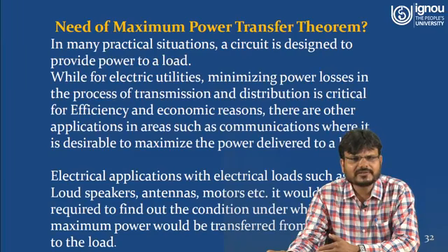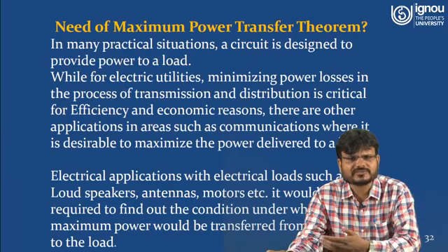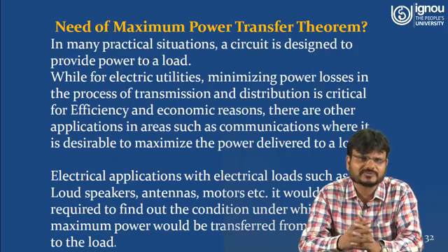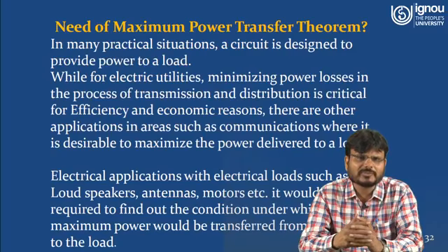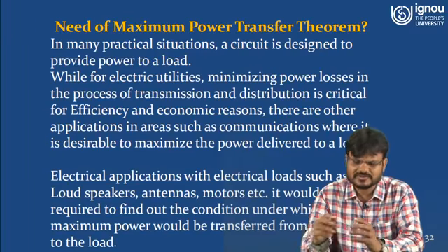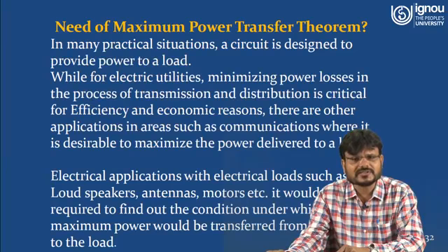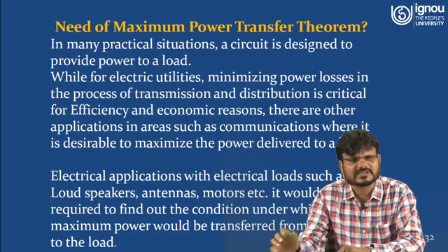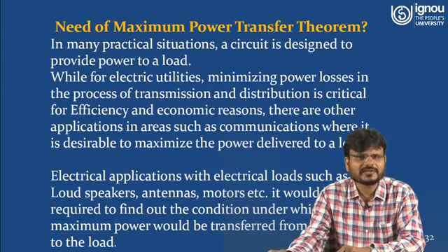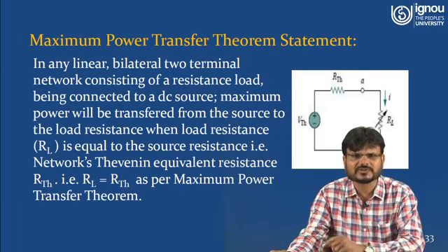It would be required to find out the condition under which maximum power would be transferred from the circuit to the load. So in the communication circuit, there is an importance of the maximum power transfer theorem. But if you are talking about the power system, this maximum power transfer theorem is of no use. So for the communication circuit, suppose you are using a loudspeaker, that means you have to transmit the maximum power. How this maximum power can be transferred from source to load can be understood with the help of the maximum power transfer theorem.